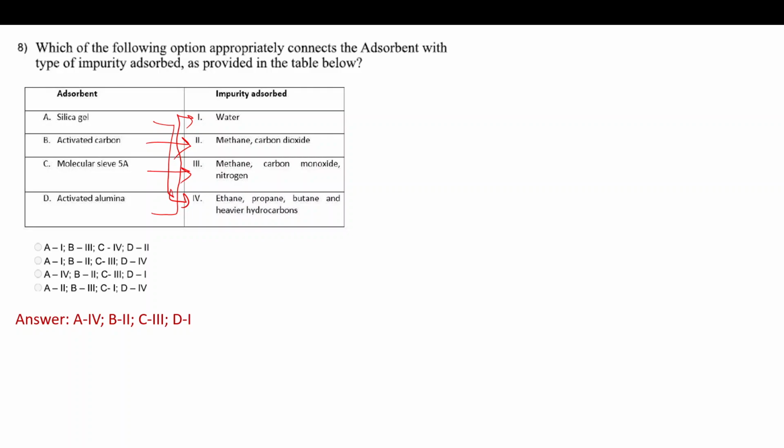You can look into that. The next question is, what is the aspect ratio for a five field electrostatic precipitator having collection plate height 30 feet and collection plate length 9 feet? The width is given as 50 feet, which is normal to the gas flow.